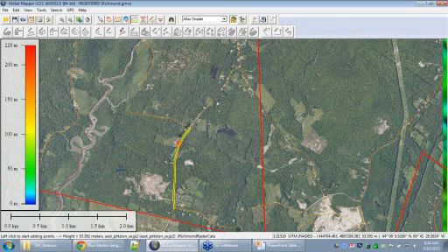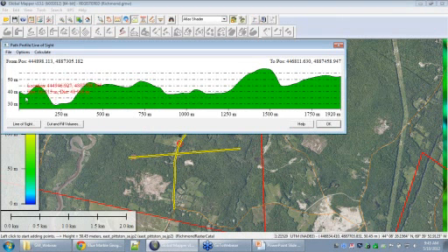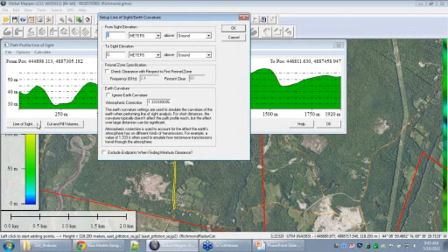If I do something like a path profile, simply digitizing, there's a path profiling tool up on the upper toolbar there. We can also simply do a path profile on a straight line that we draw across the surface. And that's going to give us a starting point and an ending point. You'll see there's no individual little nodes along the surface because I don't have vertices along that line. I just did a quick little 2-point line here. And with that 2-point line, I can do a line of sight calculation from the start point to the finish point of that line that I just drew.